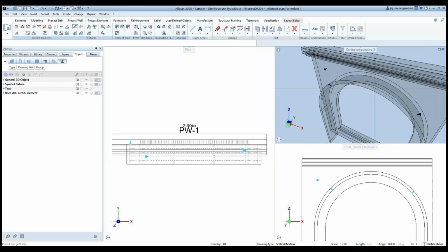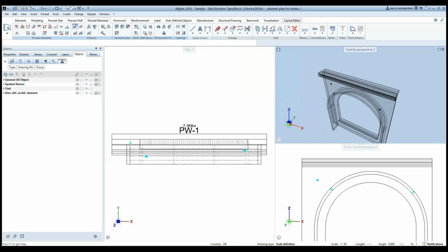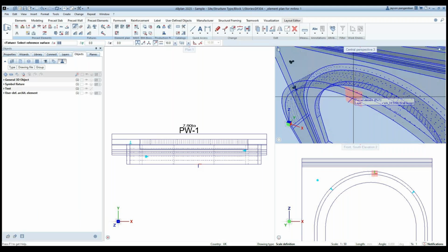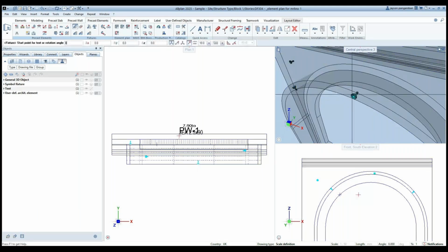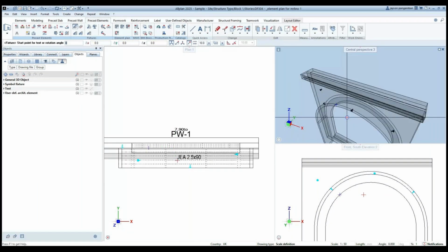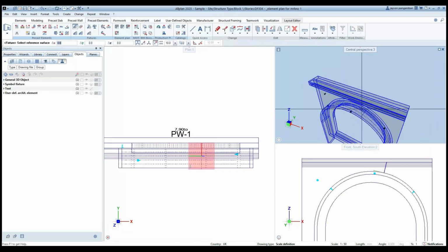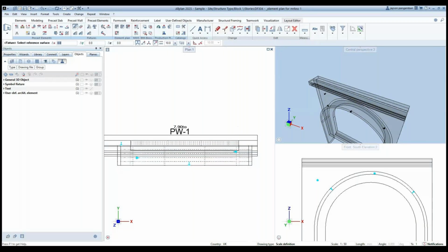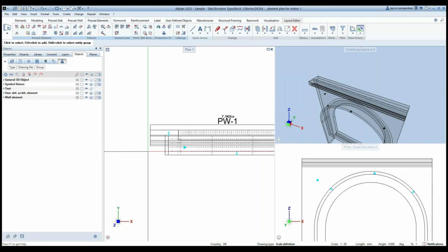So even, let's say for example at this area, I need to place again 3D, select 180 degrees and maybe in this surface. As you can see, it detects your fixture or the surface of your element. So this is much easier to place now compared to before, because before we needed to create different views just to place the fixture.